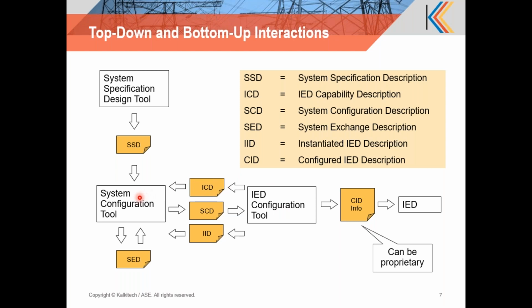square one. When you import that ICD file here into the existing system configuration, you need to perform all the configuration steps that you had performed earlier, and you need to ensure that you do not deviate from what the rest of the devices were expecting. So obviously, the solution was for the IED configuration tool to export not an ICD but an IID, which contains all the configuration that had been earlier provided by the same SCT, along with the changes that it has made. And now the SCT can import the IID, merge the content, and resolve the few things that have changed. So that is our take on what is now being called top-down and bottom-up engineering.